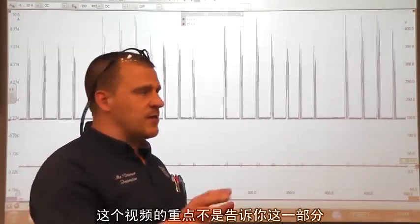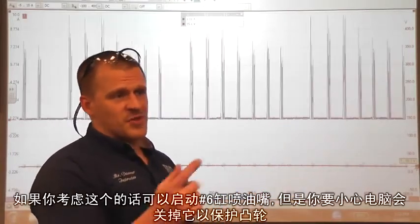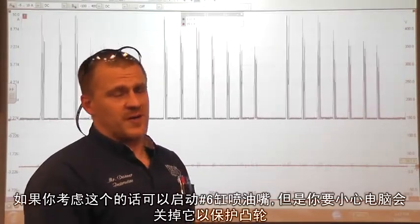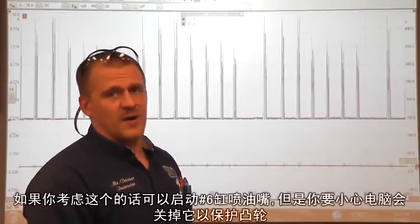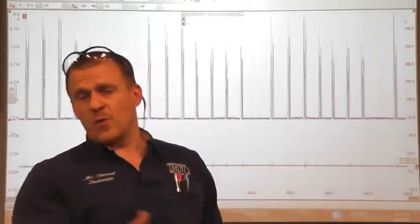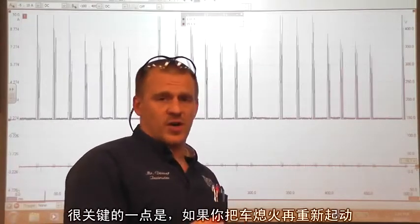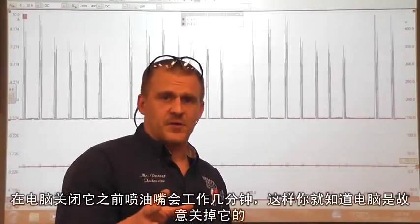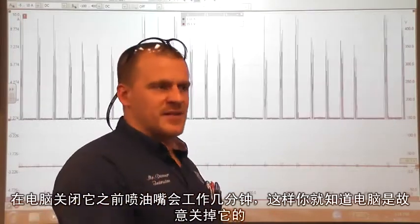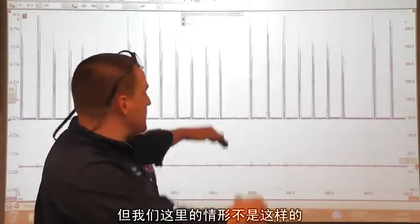My focus for this video is not to show you that part. But if you think about that, and you started with a fuel injector on the number 6, boy, would that throw you for a loop, because the computer will shut the injectors down to protect the cat. So you have to be careful with that. One of the keys to identifying that, though, is when you shut the car off and restart it, that injector will fire for a few seconds before it shuts down again. And then you can see that it's an intentional shutdown. In our case here, that's not the case.